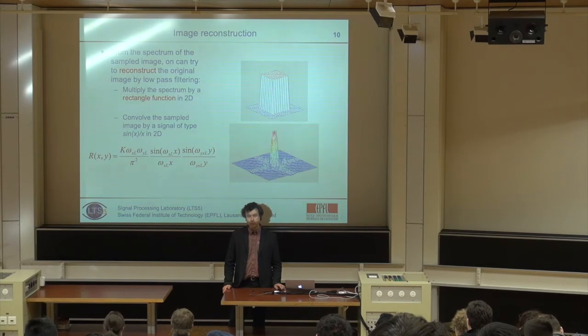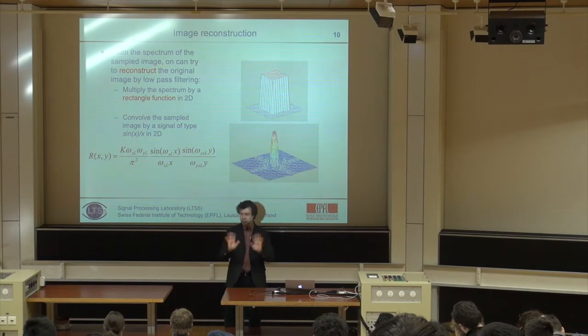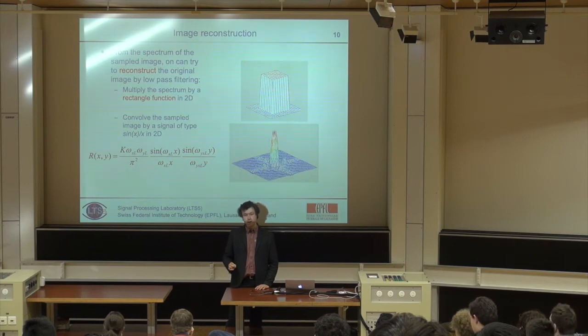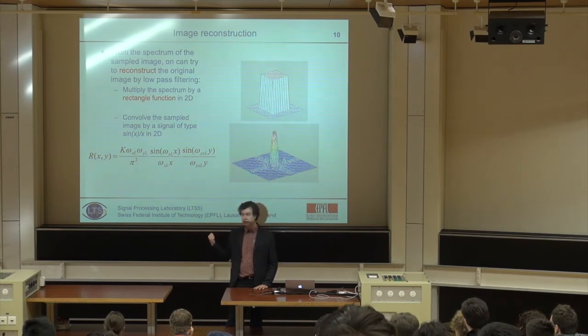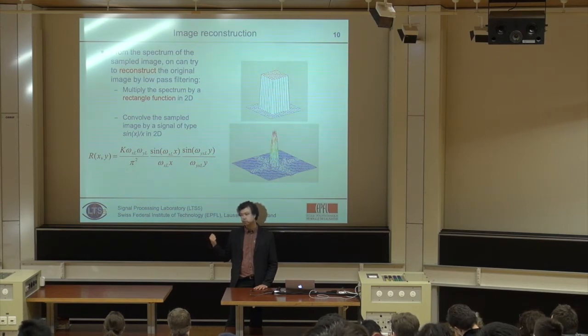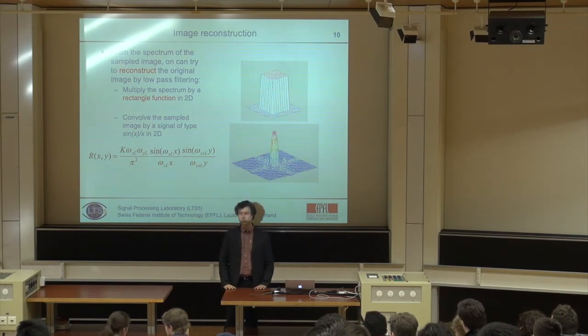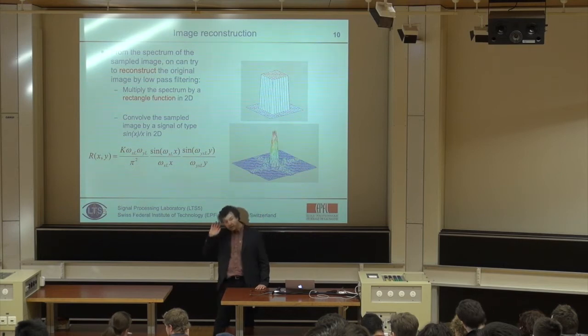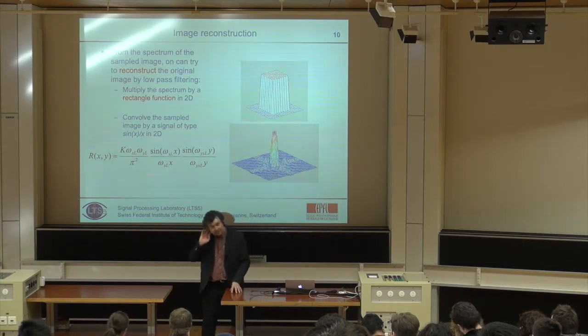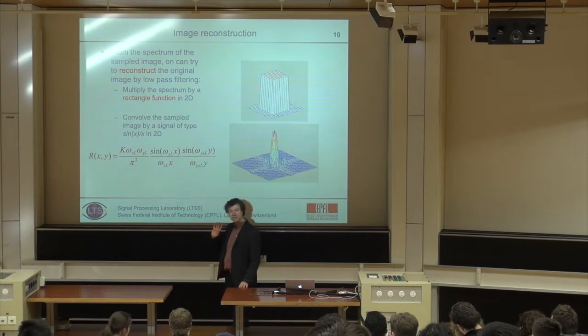Where is the problem? It's true, under the assumption that we sampled with the right frequency, that's okay. You can really find the exact value, but what is the problem? How would you do that? By interpolating with that kernel, right? What is the problem with a sinc kernel? It's not bounded. Yes, it has an infinite support.